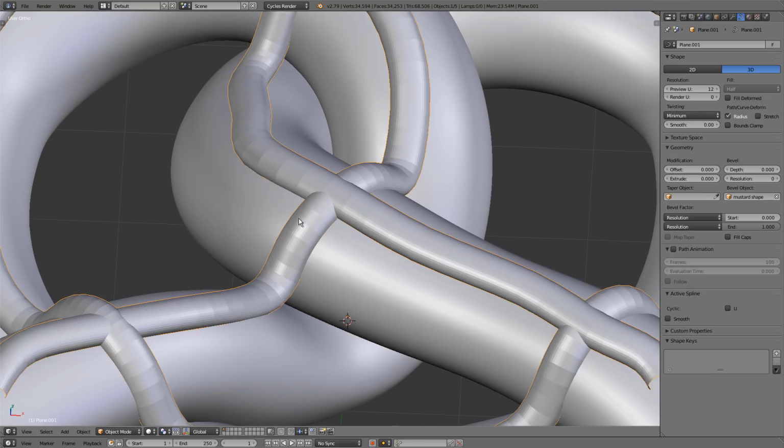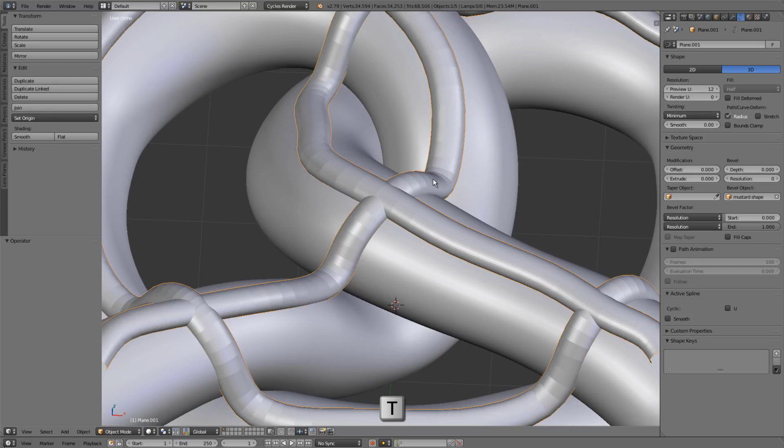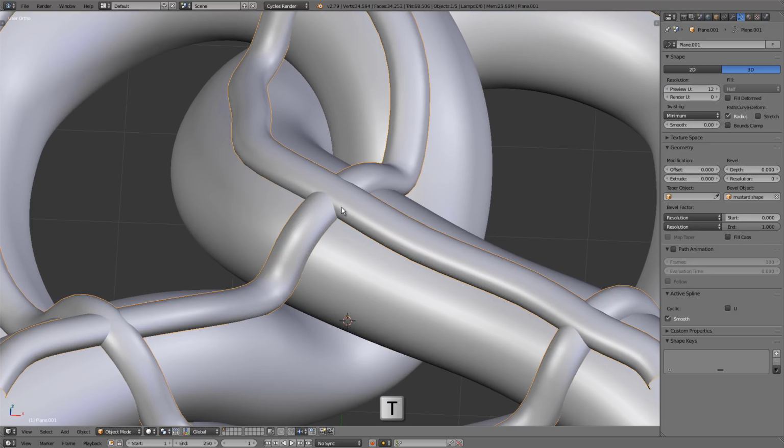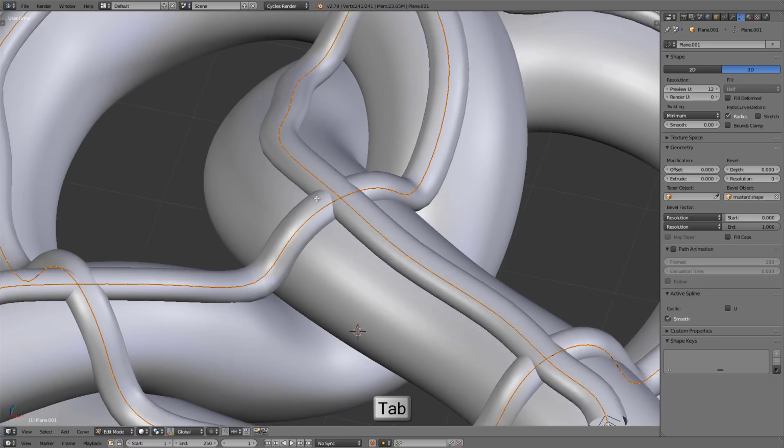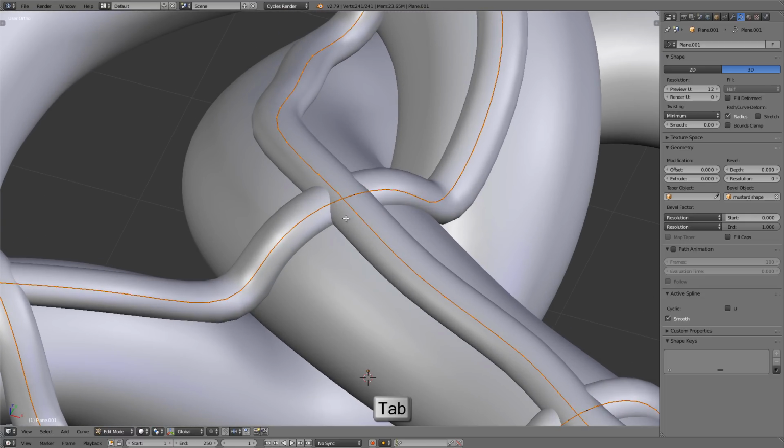Now the first thing I'll do is smooth out this faceted look. So let me press the T key for the left side toolbar, and with this object selected in object mode, we can then go up to the Tools option here and click on Smooth Shading. Let's press T to get rid of that. And let me tab into Edit mode. And what we're going to do now is use Connected Proportional Editing to bump up these ropes of mustard over one another. So let me go down to the Proportional Editing menu here and enable Connected.